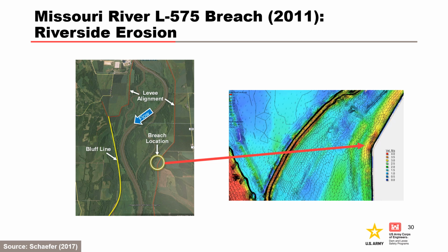Vegetation in the floodway can be naturally occurring or planted in riverside borrow areas. This vegetation can constrict and concentrate flow along the levee alignment, leading to riverside scour of the top stratum and levee embankment, directly connecting the foundation sand to the river and shortening the seepage pathway. The vulnerability of the levee to scour erosion is further exacerbated when the levee alignment protrudes into the floodway or is located on an inside bend.